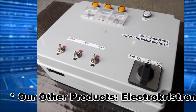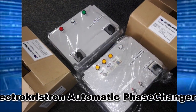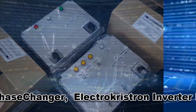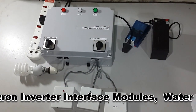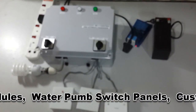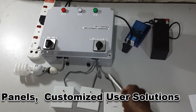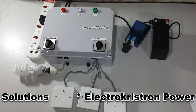Normally, if you connect an automatic changeover directly to an installation where you already have an inverter, the automatic changeover will not allow your inverter to operate, because the moment mains fails, your automatic changeover will start your generator immediately, because that is part of the internal functions.